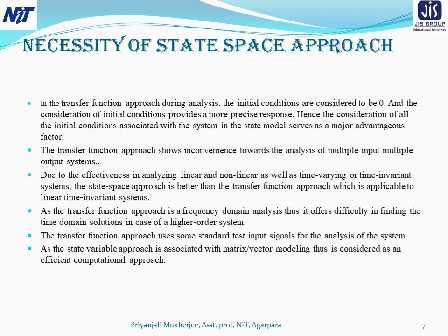Next, the transfer function approach shows inconvenience towards the analysis of MIMO systems. That means it is only applicable for SISO systems. Not only that, but the systems should also be linear and time invariant. That means if a system is a MIMO system, or multiple input multiple output, or a nonlinear system or a time variant system, then you cannot apply the transfer function model.